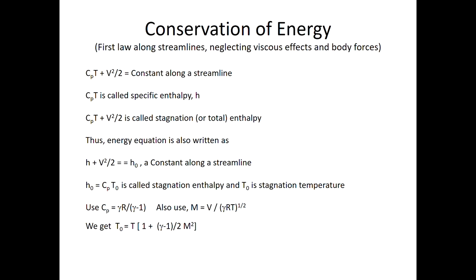In an inviscid flow, in the absence of viscosity, in the absence of body forces, in an adiabatic flow, stagnation temperature remains constant, even across a shock wave. So this is what the first law of thermodynamics gives for a compressible flow as an energy equation.